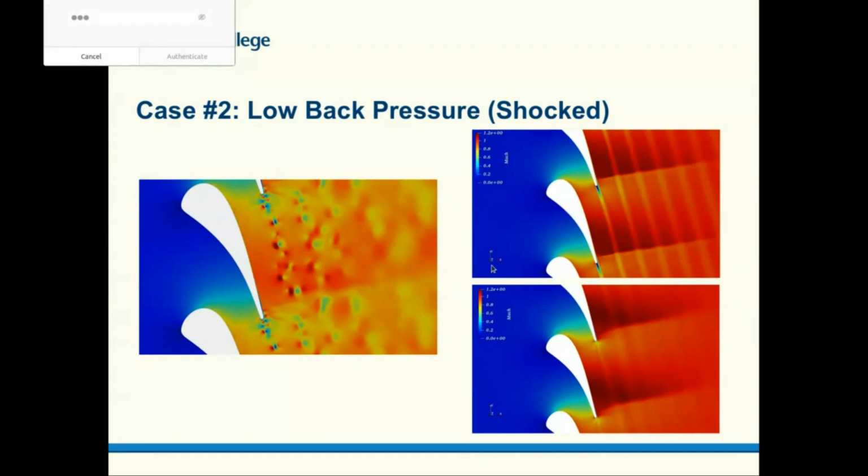And to sort of show you the importance of using these methods that allow you to sort of resolve flow features correctly, I've put on the right hand side a standard time average RANS solver and an unsteady Nektar++ time average solution, and you can see the difference. Despite being at the same conditions and same boundary conditions, you do see the shock being effectively a straight line in the case of the RANS solver, so less accurate, whilst if you time average an actual set of instantaneous solutions, you get sort of the right shape, because the thing is oscillating above the boundary and interacting with it